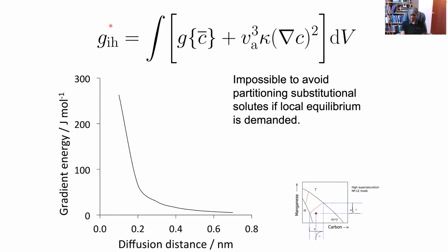So let's just look at experimental evidence for the NPLE method. And I claim that NPLE has never been observed experimentally in kinetic data, where you measure the thickening rate of allotriomorphs as a function of time. And one of the most important reasons is that the real structure of an allotriomorph is far more complicated than one-dimensional or two-dimensional thickening, etc. So we have the classic prediction that Smith made of a curved interface here and a faceted interface.